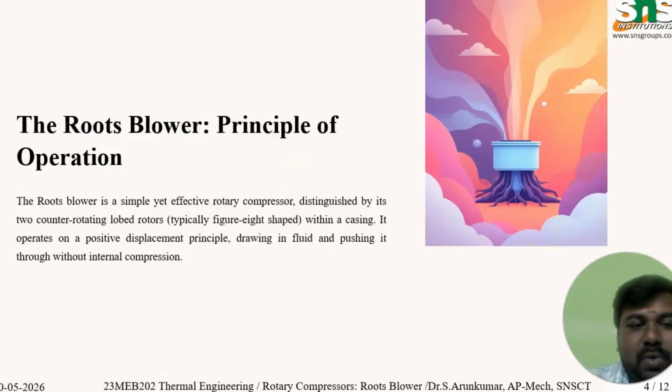So the roots blower, let us discuss its principle of operation. The roots blower is simply one type of rotary compressor. It is distinguished by its two counter rotating lobed rotors, typically figure 8 shaped. Within the casing, it operates on a positive displacement principle, drawing in fluid and pushing it through the throat without internal compression. This is the principle of the roots blower.